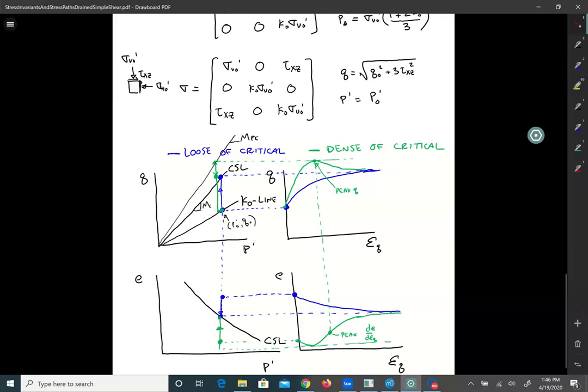Dilation has the effect of actually having sand particles, if we're thinking about sand, moving uphill. And if you're having to push them uphill, you have to push them harder than if you have to push them on a horizontal plane. So the slope of the hill is like this slope. You can think of it physically like that. When that slope reaches a peak value, that's when it's hardest to push the sand uphill, and you're going to get the peak in the stress strain curve right there.